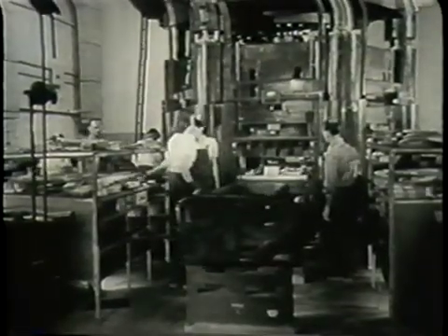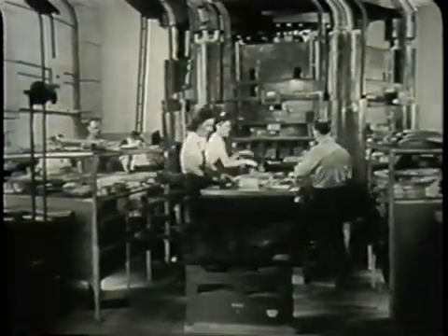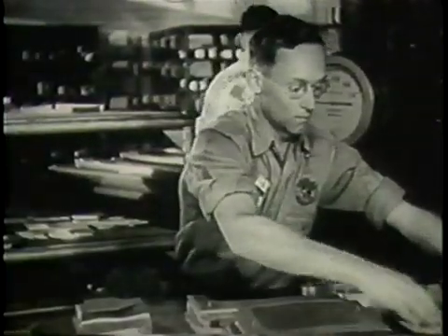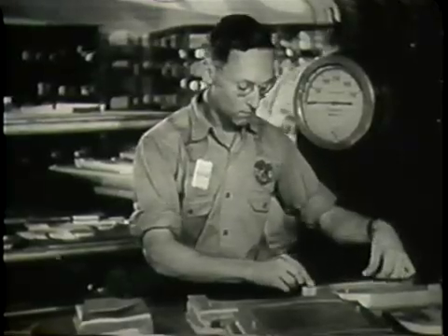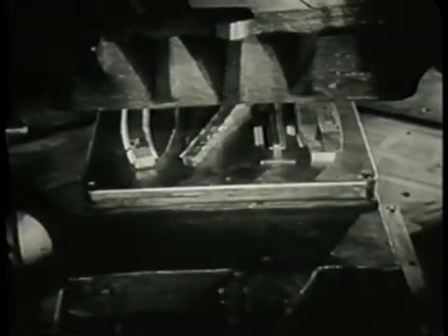The bending or shaping to double curvature of a number of parts at once is accomplished by use of a hydropress. The parts to be formed are loaded on a table, the alloy sections being placed on forming blocks or dies. The table is moved under the press, the action of which is single and continuous.